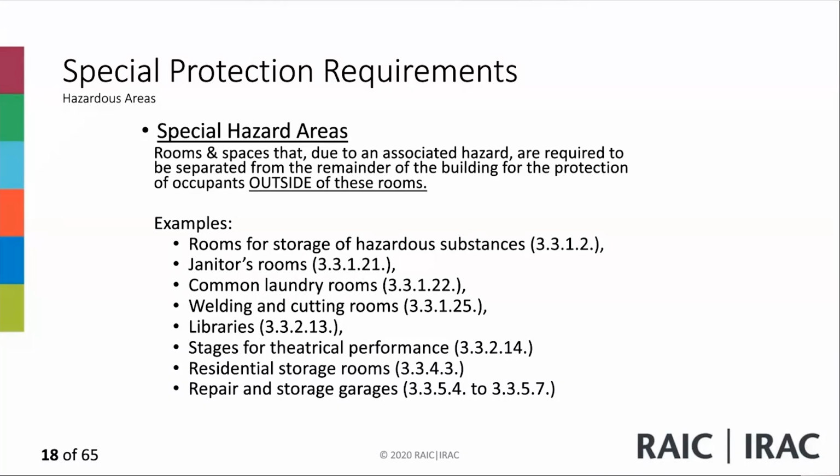No. Okay, so a repair garage and any ancillary spaces serving it, including waiting room, reception room, tool and part storage areas, and supervisory office spaces, shall be separated from other occupancies by a fire separation having a fire resistance rating not less than 2 hours. So a repair garage, with all its ancillary uses, must be separated from other occupancies by 2 hours. Is that clear?